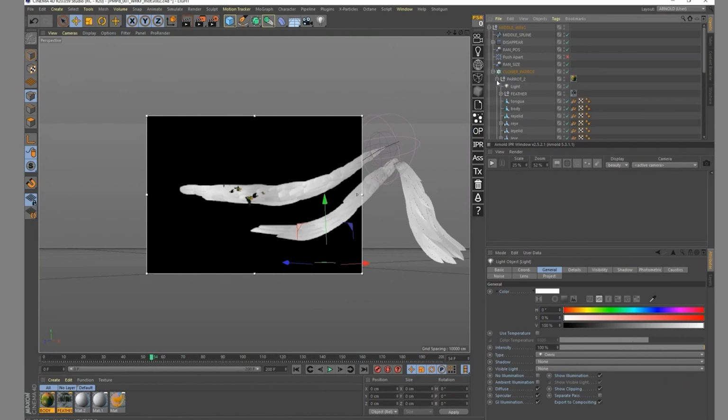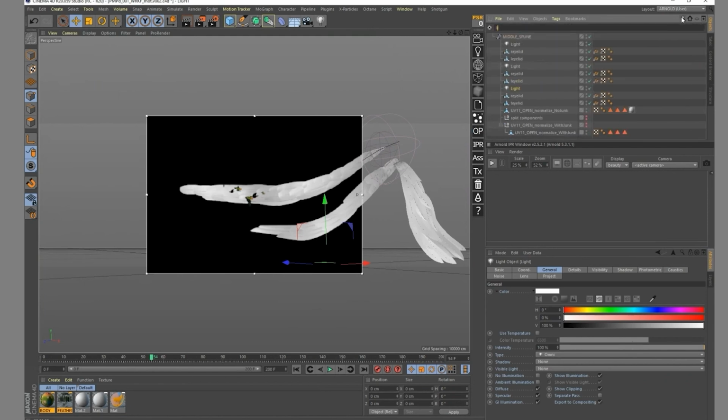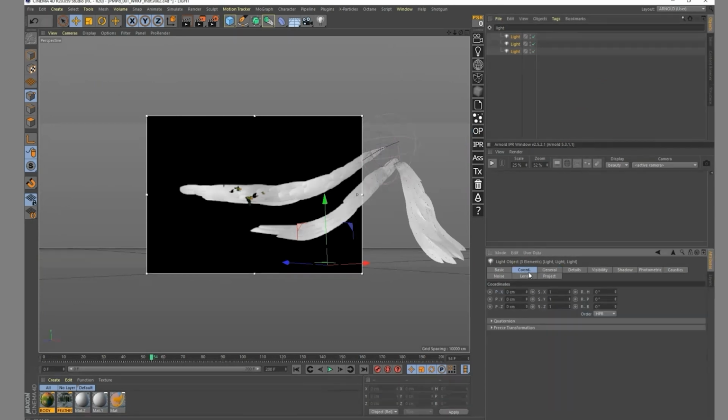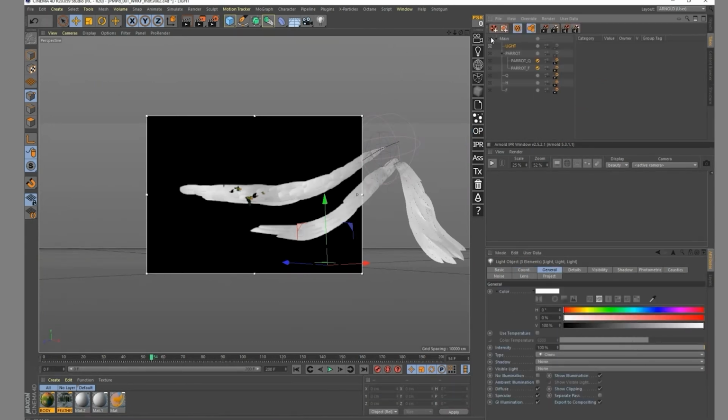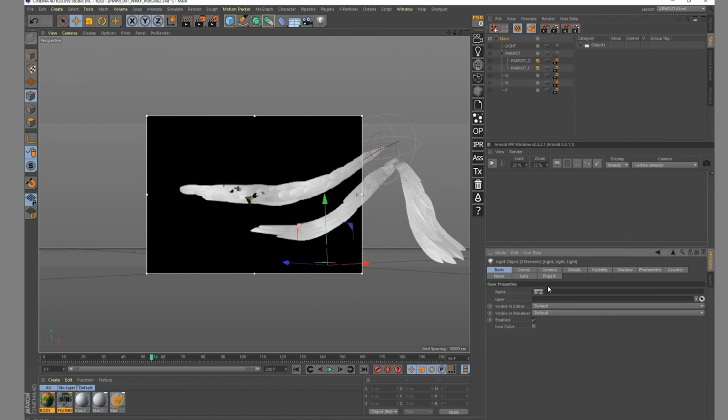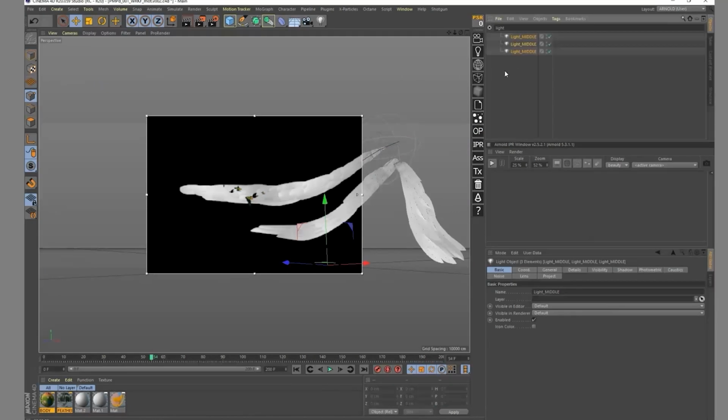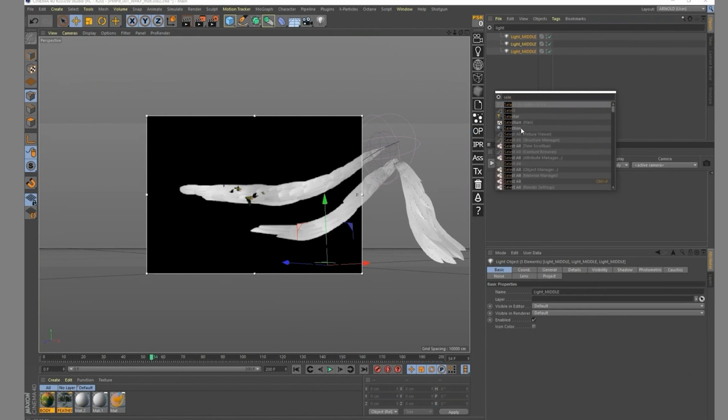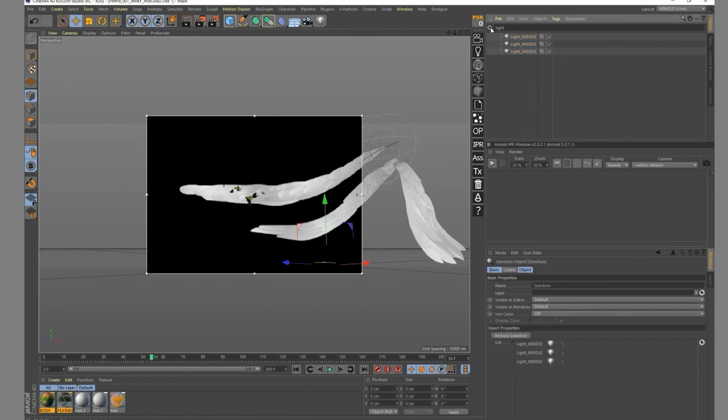One easy thing that I can do is just select all those lights, rename them, of course. I'm just gonna go back to the main take to be sure that my modifications are gonna be put in everything. So I'm gonna output that light middle. So that's fine, all the name changed. And now if I select all of them, I'm doing Shift C, and I'm gonna create a selection out of that. You cannot see it because it doesn't have the light inside of it.